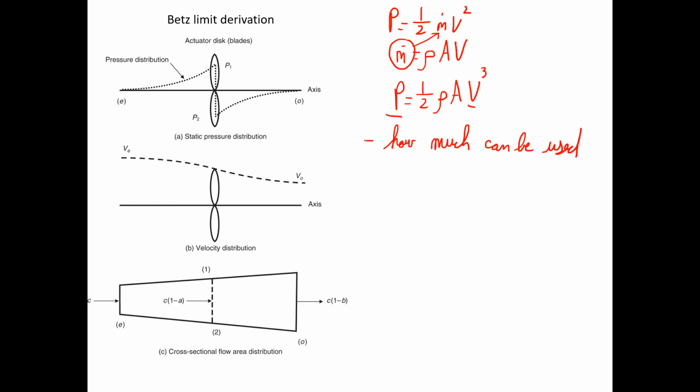There is a way to quantify that, and it is done by what's called a Betz analysis. The limit to how much energy you can pull from the air is quantified by the Betz limit. So let's go ahead and do a Betz analysis, right? We're going to start first. Let's define what the actuator area is. We do that with pi divided by 4 times the rotor diameter squared. And again, that's what we would call the actuator area.